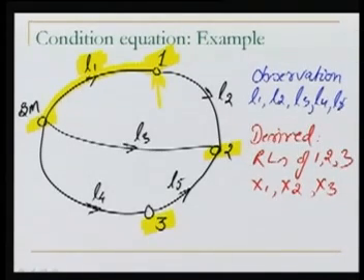Further, because we have to determine RLs for 3 points, I can go further to point 2 by observing this L2, then one redundant observation L3, because now this L2 can be computed through this route as well as this route.